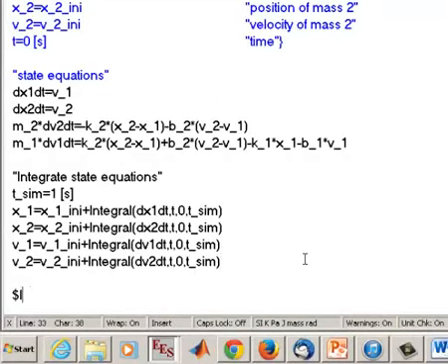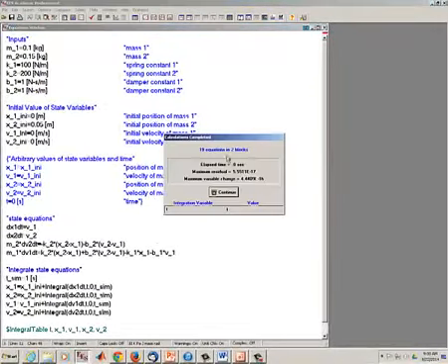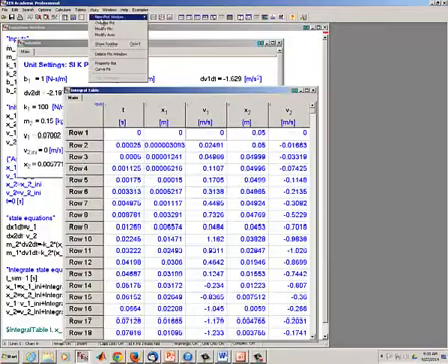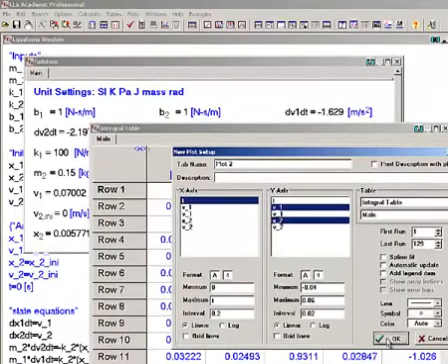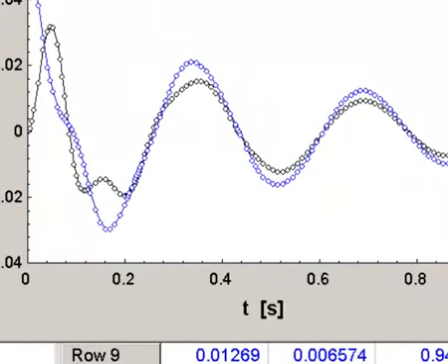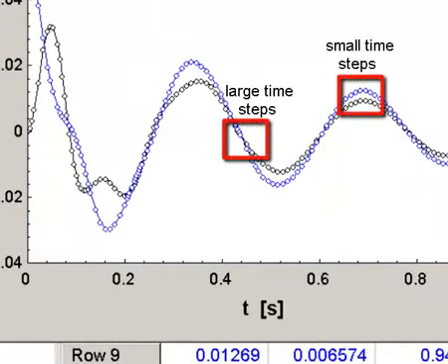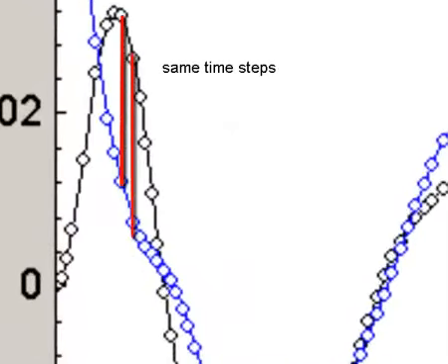Let's use the $IntegralTable directive to create an integral table that's going to store the results for every time step. Solving then leads to the integral table shown here, and the positions of the two masses are plotted as shown here. Notice that EES has selected time steps adaptively in order to maintain accuracy while being as computationally efficient as possible. However, you should also notice that the integrals are computed together, and therefore they're all utilizing the same time step and must also have the same limits.